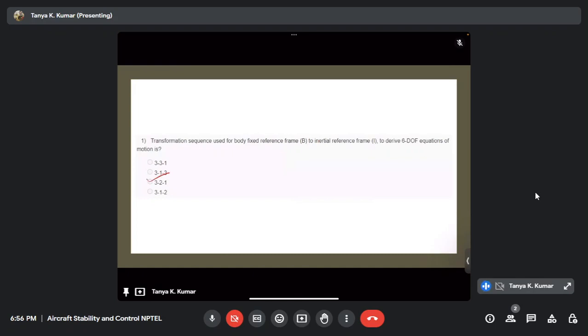Okay, now the next question. The rotation matrix for wind axis system to body axis transformation. Wind axis. When do we use the wind axis? The wind axis is for the relative velocity. What is it also called? When do we use this? You can see that the angles alpha and beta come into play here because of the wind axis. Otherwise it will be phi theta psi. Now you have alpha and beta.